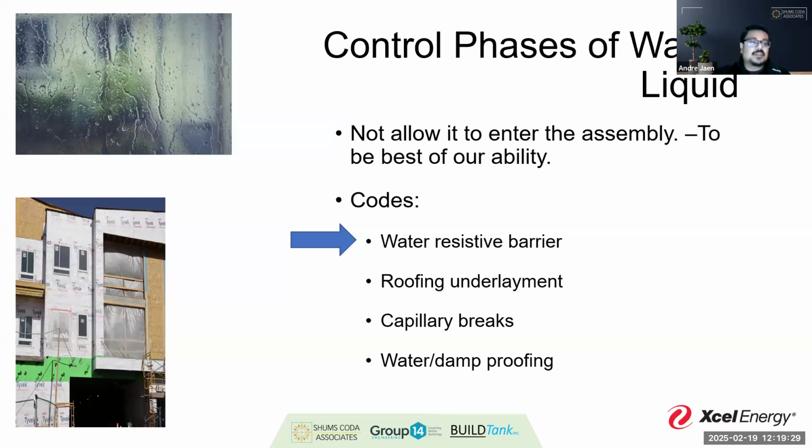These are capillary breaks. So anyone who has worked in concrete, for instance, knows that concrete can act as a wick. It will draw moisture through. It is permeable in that sense, and water does want to pass through it. That's why we moved to doing things like treated lumber for our sole plates, right? And we started using things like sill seal for a capillary break on some of those, and that's why we get our designs for our foundations the way that we do as well. When we look at our footing and stem wall, which sometimes will incorporate a capillary break, and of course our waterproofing and damp proofing, which we can definitely see in some of those humid places that we worry about, like crawl spaces, where that difference is really profound, really significant.